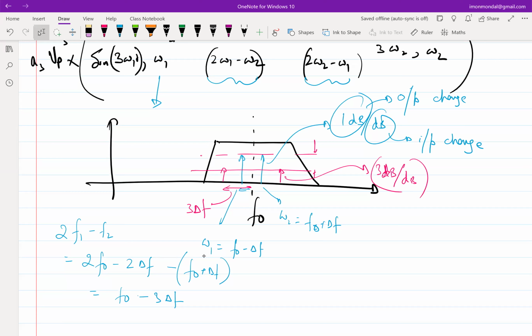So clearly you see that if you're not careful, this red tone can catch up with the blue tone for reasonably high amplitude of the input, right? So that's why anything that is connected to the front end, it becomes imperative to characterize it for good amount of linearity, right? When I say good amount of linearity, we'll define what I mean by good amount of linearity. But essentially, you get the idea why it is important. Okay.